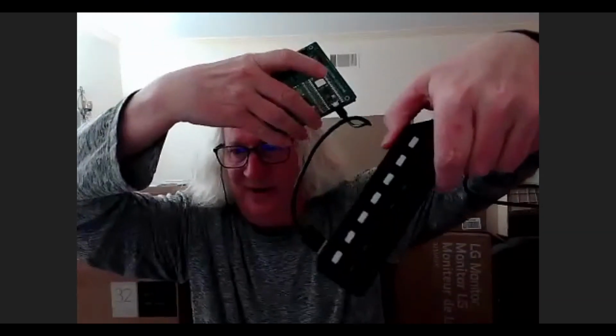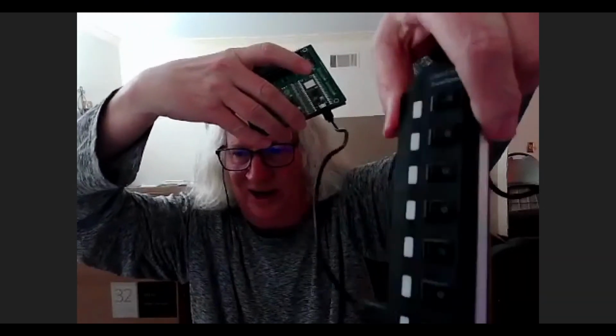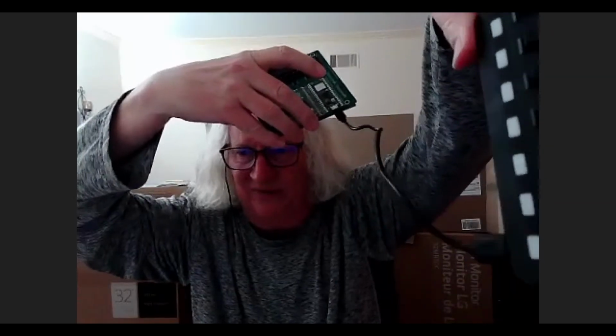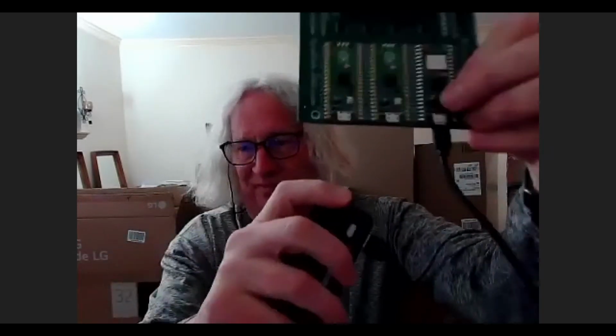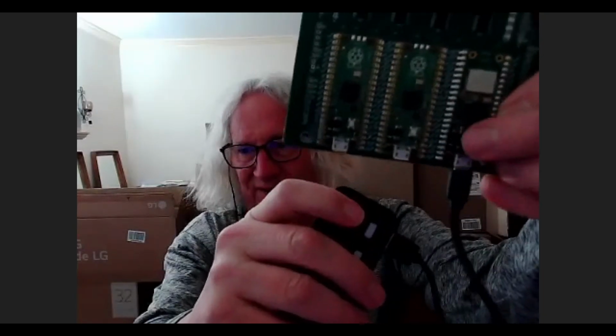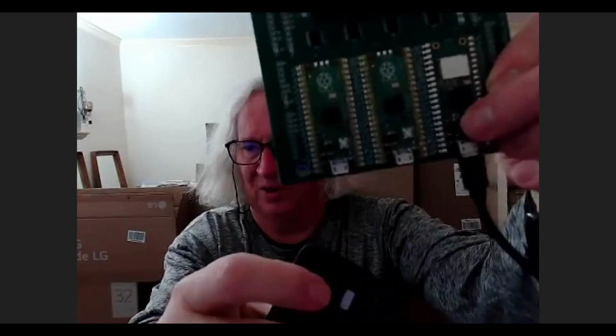Okay, so I have a cable with switches on it here for a USB hub, which is really convenient. Otherwise, you have to plug these in and out in order to reset and reboot, and just flipping the switch is convenient. So I'm going to hold down the little button that's the bootload button while I power it up by flipping that switch, and it made that sound, which means that it has mounted itself as a disk drive.